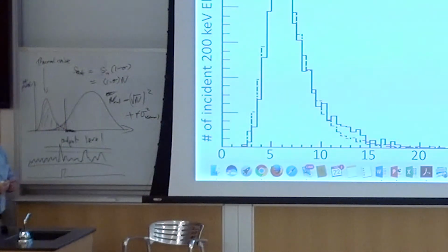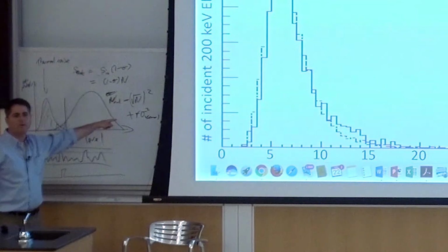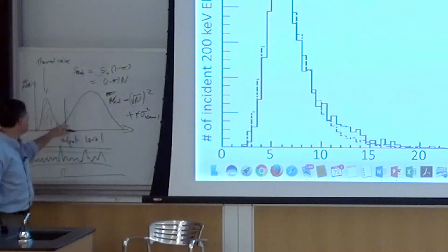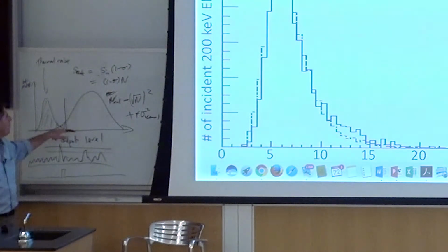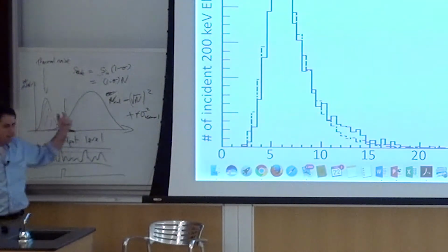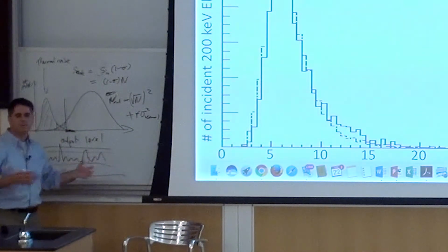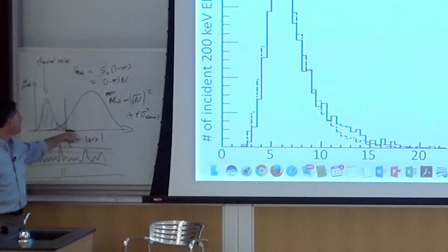And that too impacts the signal at low count rates. So now if I'm at very low count rates, eventually I'm going to miscount this piece. This one tends not to be a big deal because it's actually quite small. It's there, but you'll only notice it if you're trying to run your K2 as a pixel array detector, because then I'm summing over tens of thousands of pixels, and then these tails add up and mess me up.